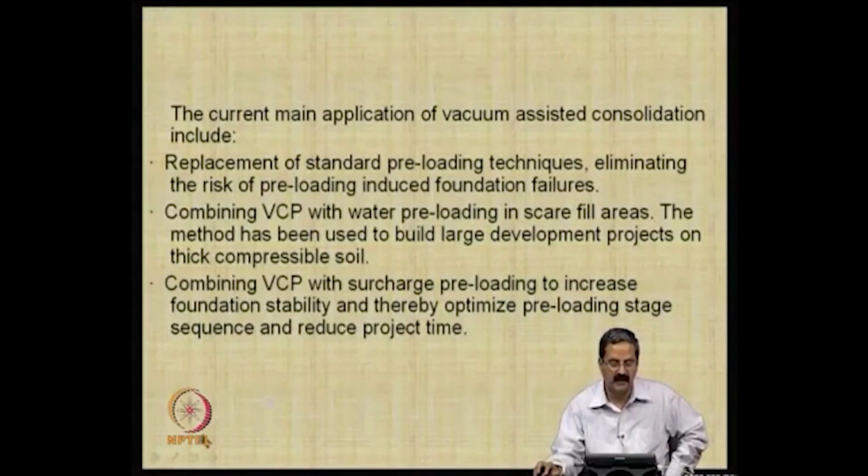So, what should be done? You try to combine vacuum consolidation preloading with both. You can have both of them in areas where there is a scarcity of fill. The method has been used to build large development projects on thick compressible soil, combining VCP with surcharge preloading to increase foundation stability and thereby optimize the preloading stage sequence and reduce project time.